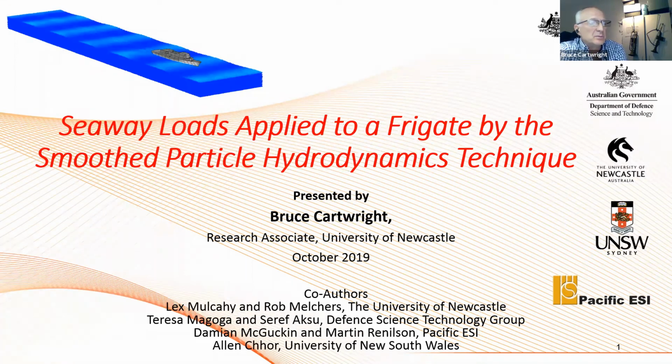Right. You saw some of the curves there, where maybe we're a little bit down on the bending moments, but some of the other results that we have been able to compare were some stresses in the top plates and in the bottom plates, and we're getting very good correlation. I'm not too sure if those results came out of Maestro, but I thought they did, and they were well within the 10 or 15%, which I would have thought for such a different approach to solving the problem is a pretty good result.